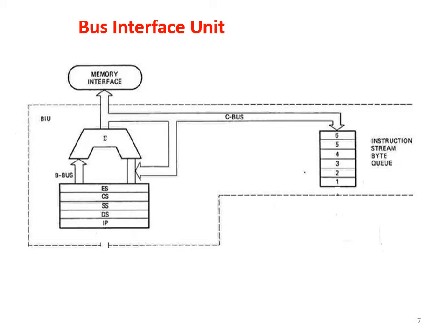And we have also seen that the total memory which can be addressed by the BIU of 8086 as a whole is 1 megabyte of memory. So in order to address 1 megabyte of memory, how many bits of address do you need? It is 1 megabyte, that means it should be 2 raised to 20. 2 raised to 20 is nothing but 1 megabyte. So you need 20 bits to address 1 megabyte of memory.